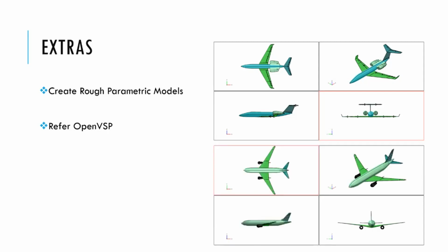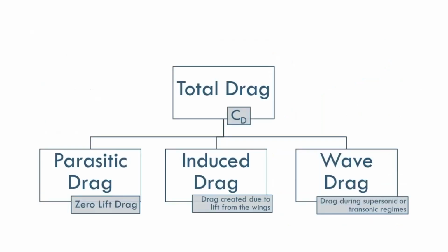So this kind of 3-view diagram we are expecting for your aircraft. We want you to determine the optimum trade-offs, and we want to refine the process so that we can get a more accurate estimate. Next, we move on to the aerodynamic analysis. Mainly, you are looking at two things: estimation of lift and estimation of drag. Both of them are through the coefficients CL and CD. For CL, there are standard procedures available. And for CD, you can look at the various drag components.